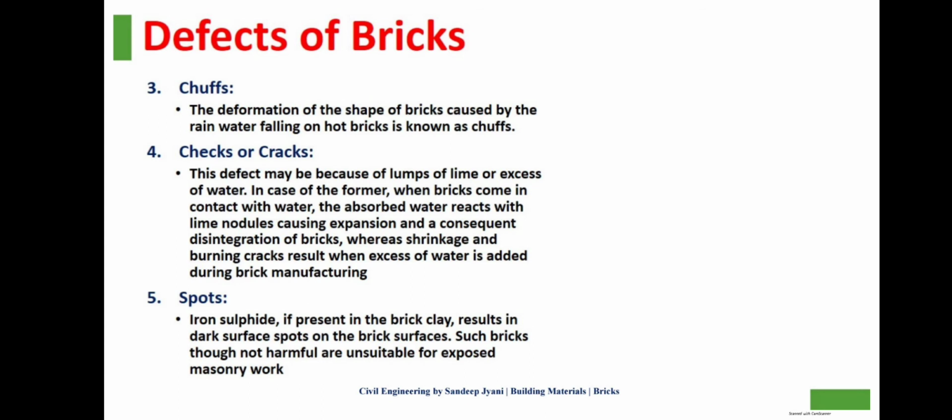Chafs. The deformation of the shape of bricks caused by the rainwater falling on hot bricks is known as chafs, checks, or cracks. This defect may be because of lumps of lime or excess of water. In case of the former, when bricks come in contact with water, the absorbed water reacts with lime nodules, causing expansion and a consequent disintegration of bricks. Various shrinkage and burning cracks result when excess of water is added during brick manufacturing.